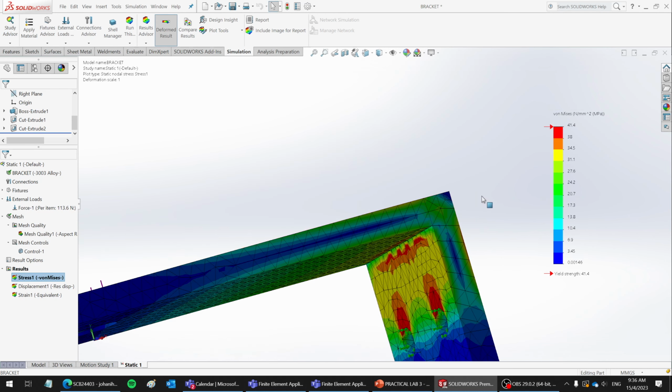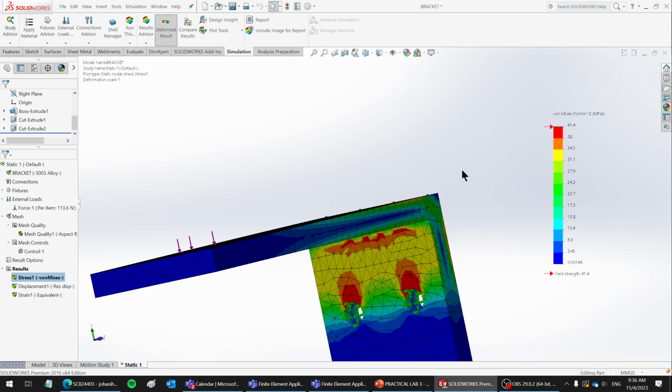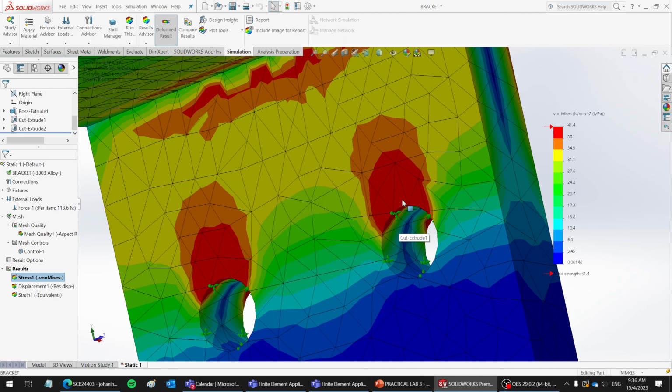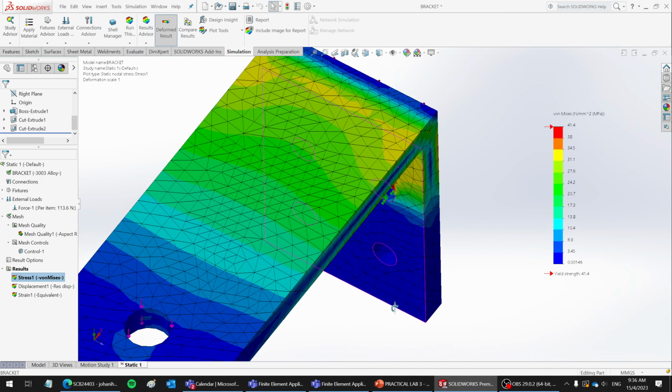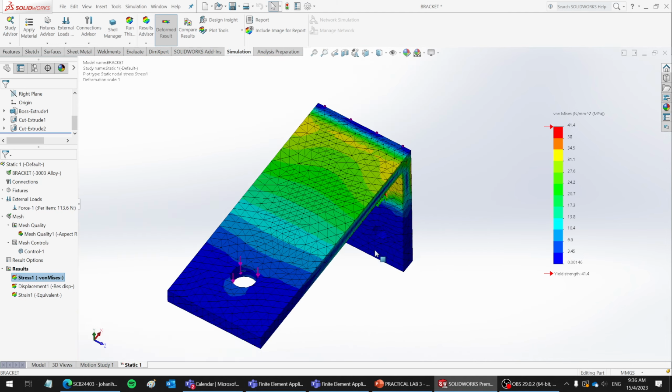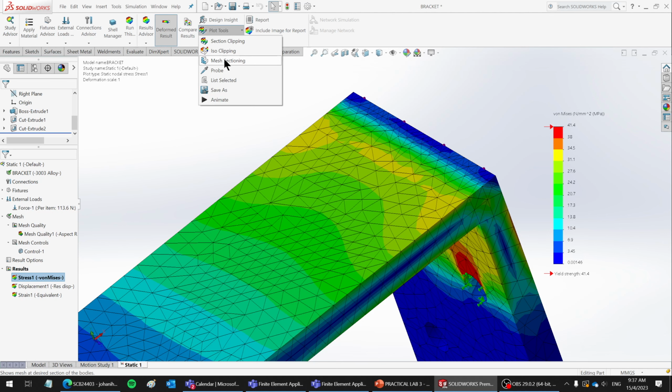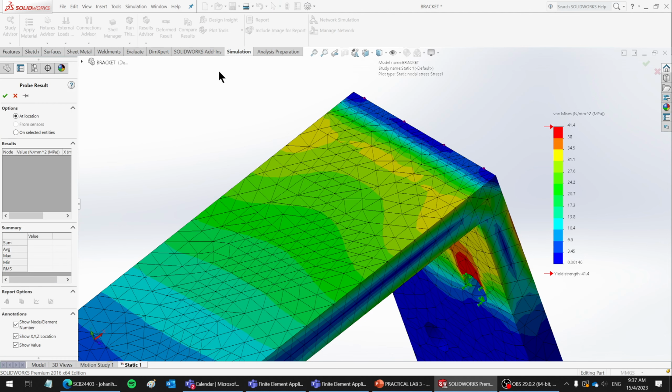So I'm getting some high stress at the regions where you have the bolts. But I believe there won't be any problem with the bolts. Why? Because you are constraining it there. So let's check out our node 7411. Plot tool, probe. Where do you want to probe? Can be somewhere here. Let's try. Maybe here.